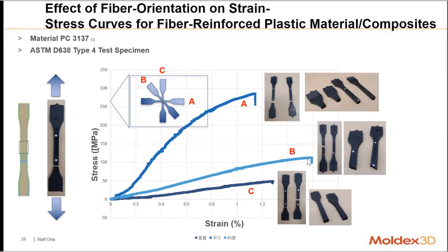And it's very funny if we check the final break point. These 2 break points are perpendicular, and you will see the break shape is around 45 degrees. This reflects the fiber orientation. Okay, so it's critical for the fiber orientations. So this kind of measurement now also can be conducted in Moldex3D, and based on this data, we can map this kind of measurement to the micromechanics modeling of the simulation.